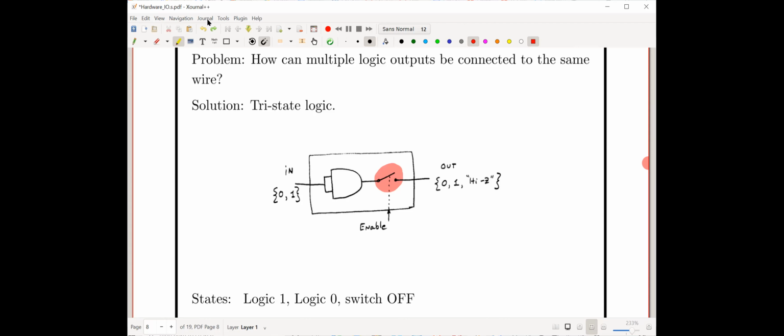Now, there's one other thing, which is that it's very common for another input to go like this. Again, this is like the bus line that's going to all the devices. And the input has no problem. You can have a bunch of inputs on a wire and they don't fight. They just listen.